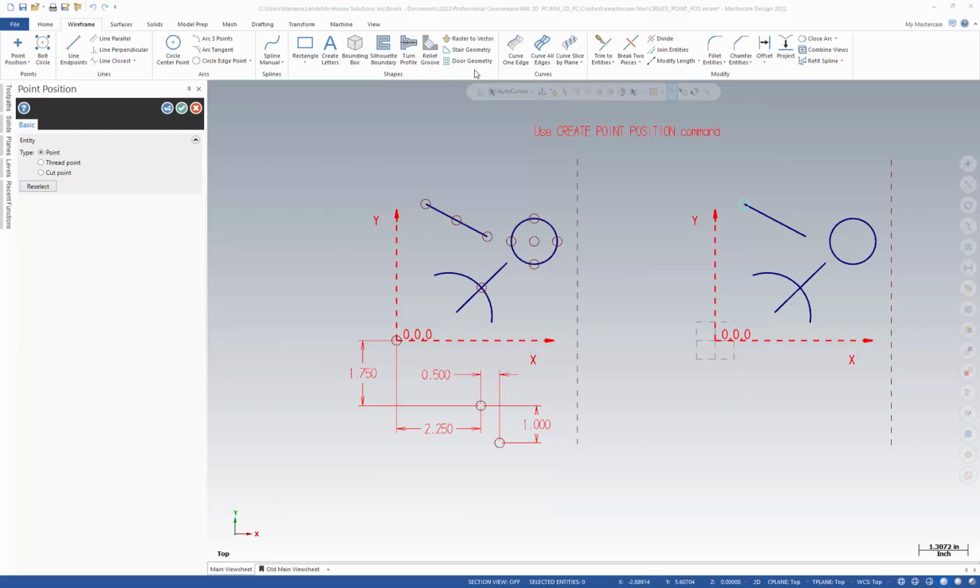If you select the OK and Create New Operation button from the Point Position panel, the point will be finished in a fixed state. You can see the change of color. The OK and Create New Operation button allows you to continue in the same command. You can also press the Enter button to achieve the same result.